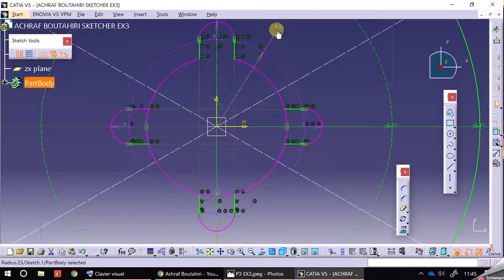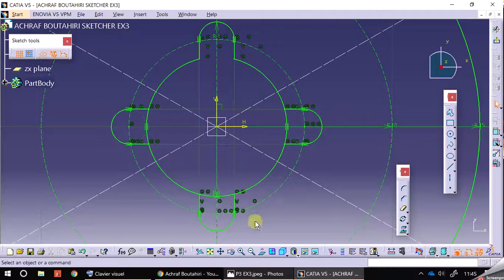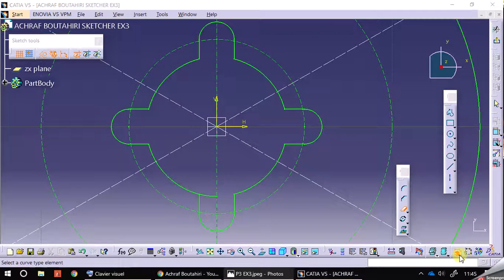Okay, so here I can delete some values. This radius, this radius, this radius, and this radius to make it auto constraints, and I delete this part like this and this part. If I hide constraint, I can see my sketch fully. Okay, just to clean up.